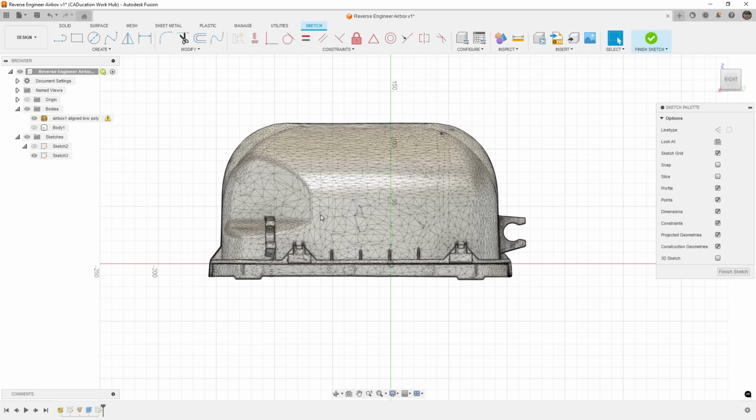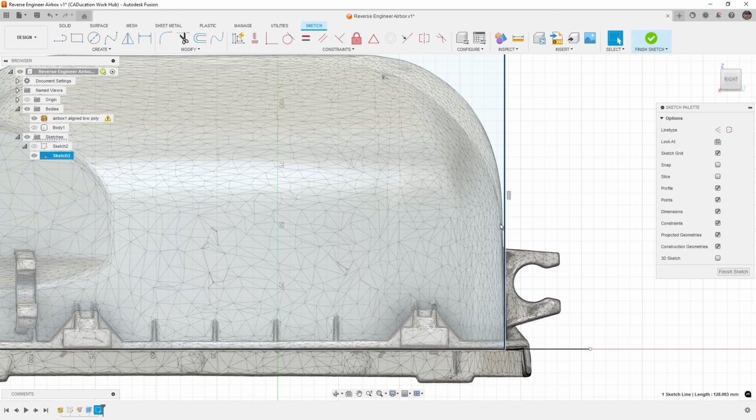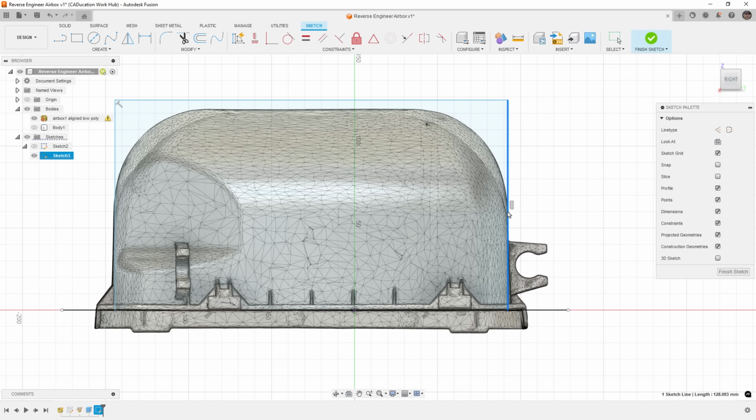Knowing that we are not creating a perfect 100% exact replica because we're not going to be able to analyze it. I'm just going to create some lines coming from the origin, make them out. And then from there, I'm going to go up vertically, come over horizontally, and back down vertically. So we'll make this line vertical and just drag it over. You can see there is a taper to it. Again, this is an injection molded part, so it is going to have draft on it. If it's textured, probably has 5 degrees of draft. For me, however, I don't think that it's really worth the effort to make it like that.